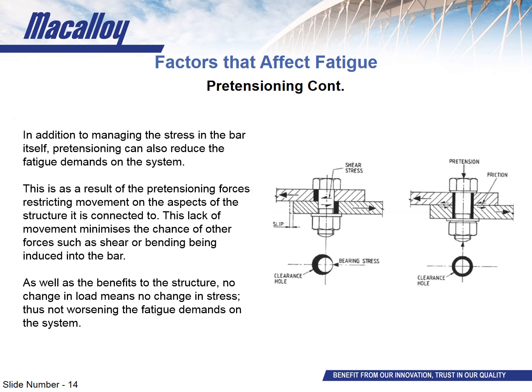The right-hand image shows a bolt that has had a preload induced into it, which in turn is clamping the two plates together. Now when the plates experience the same force as mentioned before, the friction generated by the preload prevents any movement. This keeps the bolt central and it negates any shear loading. No load imparted means that no fatigue load can be experienced, and this is true with other loading sources such as bending. This indicates that a well-designed and well-placed preloaded bar or bolts can have benefits on the structure that go beyond its own performance.